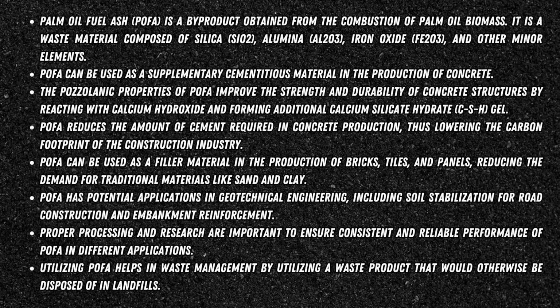The pozzolanic properties of POFA improve the strength and durability of concrete structures by reacting with calcium hydroxide and forming additional calcium silicate hydrate. POFA reduces the amount of cement required in concrete production, thus lowering the carbon footprint of the construction industry. POFA can be used as a filler material in the production of bricks, tiles, and panels, reducing the demand for traditional materials like sand and clay.